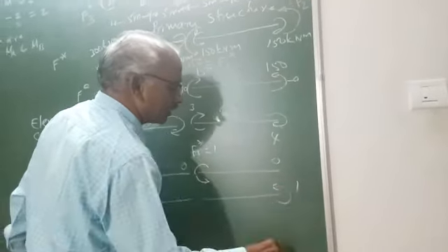Next, we have to apply the redundants. We have got only two system forces. Coming to redundant forces, we have got F3 naught. For getting the third column, we apply F3 naught equal to unity, in the clockwise direction we have assumed.